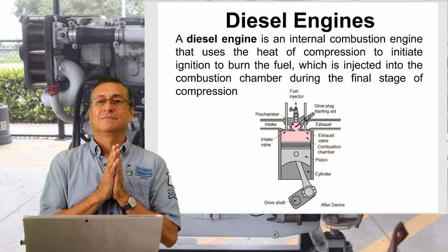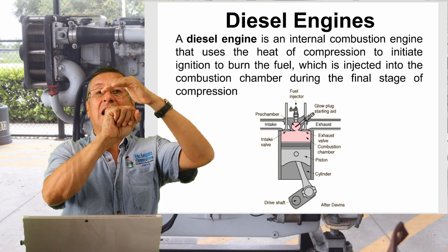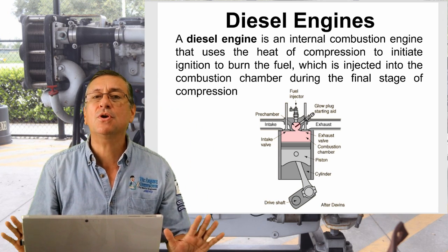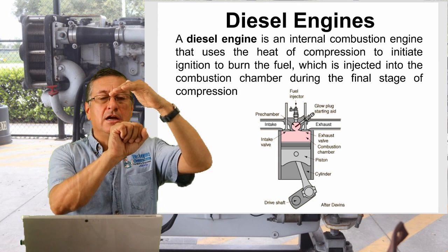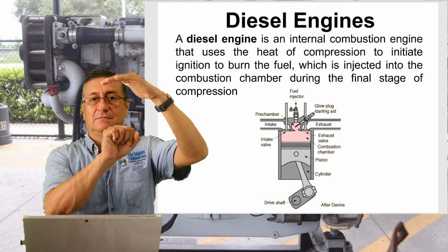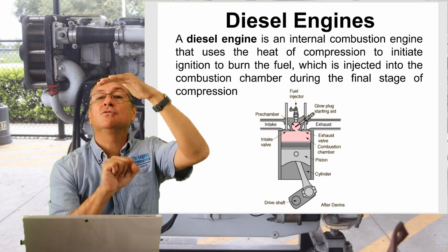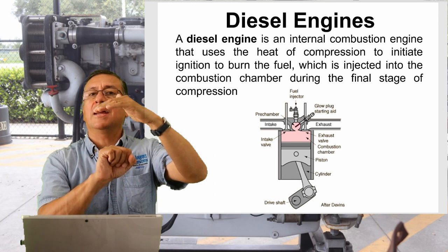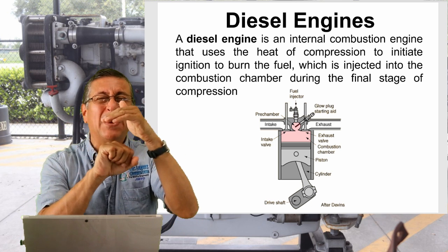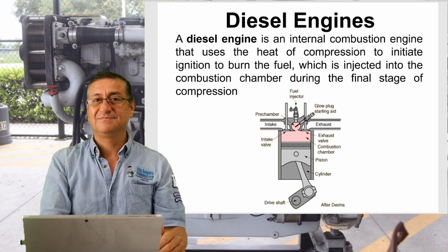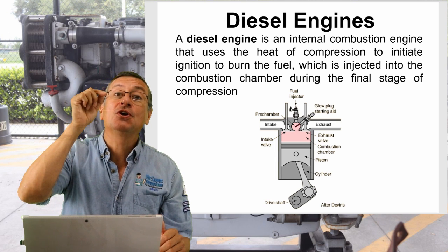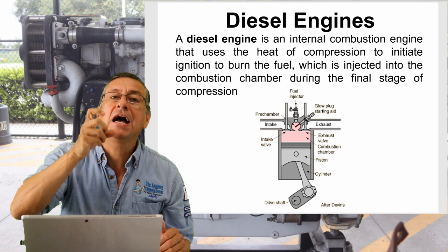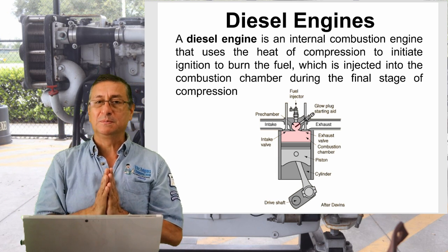All right. In diesel, when the piston is going down with the intake valve open, it only sucks in pure air, and then the valves close. When the valves are closed, the piston goes up and compresses pure air. When the air is fully compressed, pure air, the injector opens, no spark plug. The injector opens and injects, sprays, atomizes a little amount of fuel.